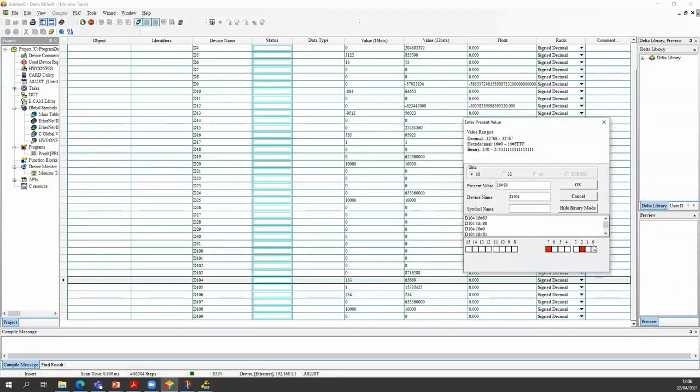If I give it another run, it's not going to run, because it only does it again if it's in relative positioning. When it's in relative positioning, it's going to go every time. But if I set it back to absolute positioning, then it's going to go 2 rotations back from 30,000 to 10,000.